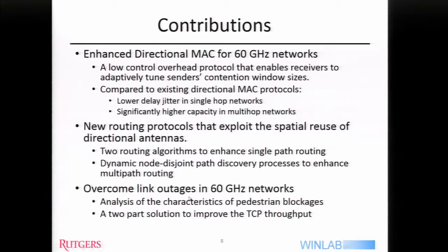And here is the summary of the contributions of my PhD work. First, I propose an enhanced directional MAC protocol for the 60 GHz. This is a low control overhead protocol, and it can achieve lower delay jitter and significantly higher capacity for the network. And based on the proposed MAC protocol, we also study the routing protocol of 60 GHz. We propose several routing protocols to exploit the spatial reuse of the directional antennas.